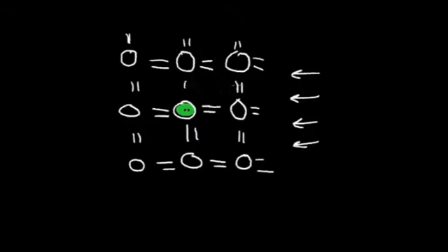The electron from this atom can go over and fill this spot and leave a vacancy here. Then an electron from another location can move in and fill this vacancy, and so on, etc. So instead of having an insulator, we end up with charge that can move around. We end up with a conductor. And the more boron atoms we add, the more conduction is allowed.